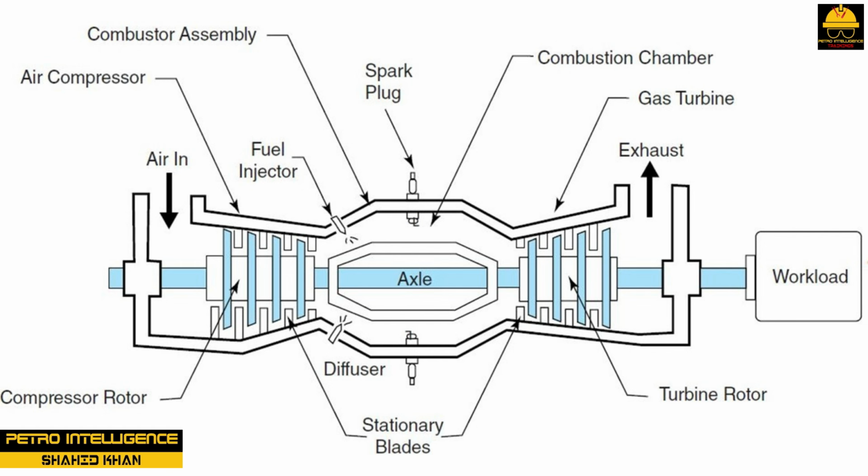The combustion chamber consists of a fuel injector, combustor housing assembly, gas fuel manifold, bleed air valve, and igniter. The gas turbine consists of a gas producer rotor assembly, power rotor assembly, moving turbine wheels and stationary blades, nozzle case and assembly, turbine exhaust diffuser, and exhaust collector. The workload consists of the driven shaft and the driven device. Each part of the gas turbine system is an integral part of the whole unit.